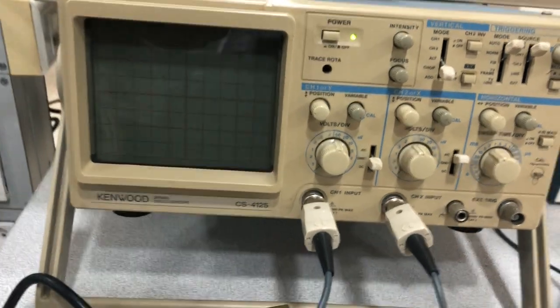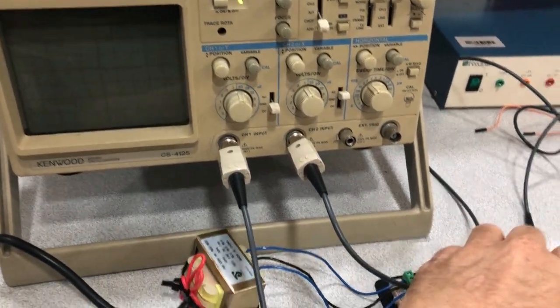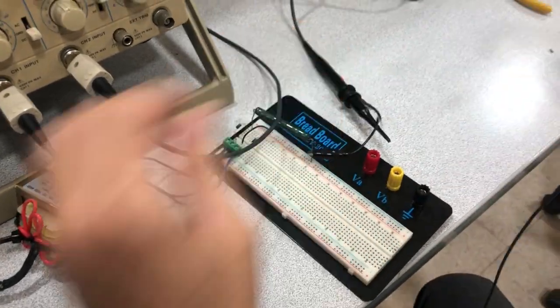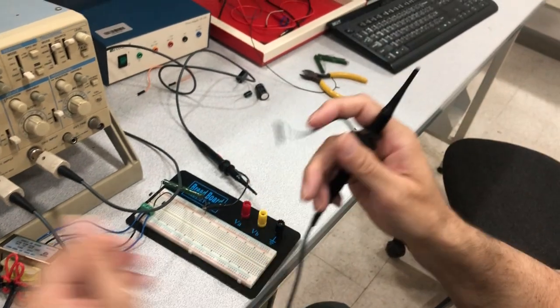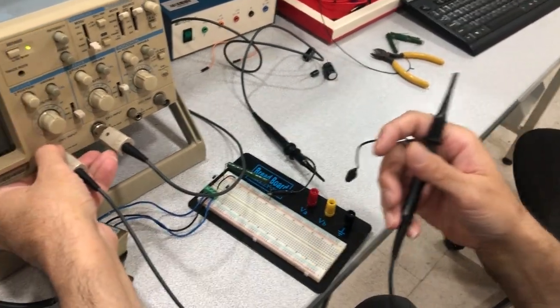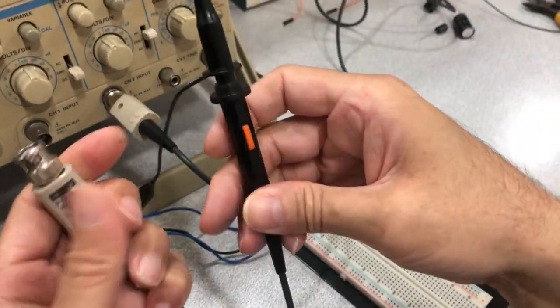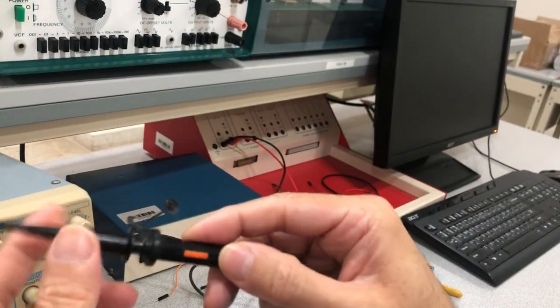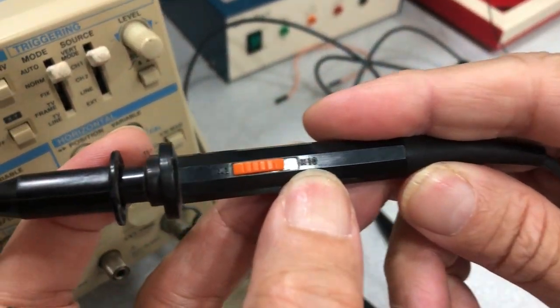The probe of the scope is not like a DMM, digital multimeter, okay? It has a thin cable, it's a coaxial cable. It has a shield and a center wire that is shielded to prevent noise from being picked up. It has a BNC connector, and this scope also has a switch, if you look carefully here, with a ×1 and a ×10.